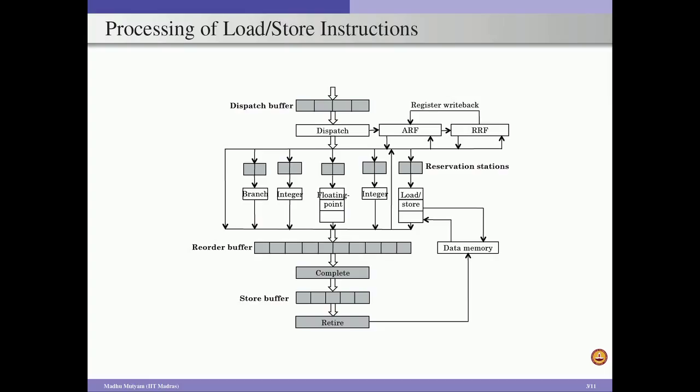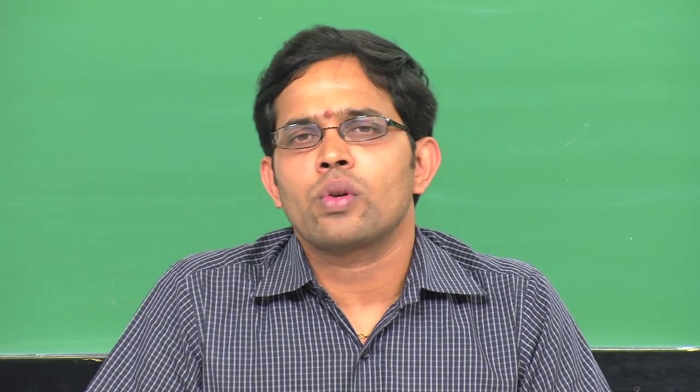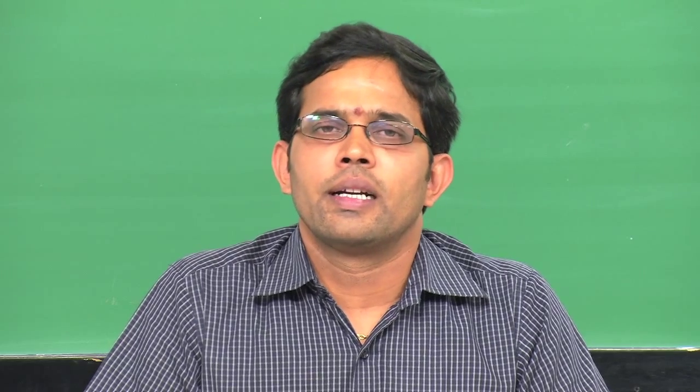We consider a load store architecture where ALU operations are performed only on registers, but the number of registers in a typical processor is limited. As a result, we cannot keep all the required data in our limited number of registers, so some of the required data will be stored in the memory, and we have to go to the memory to get those data.